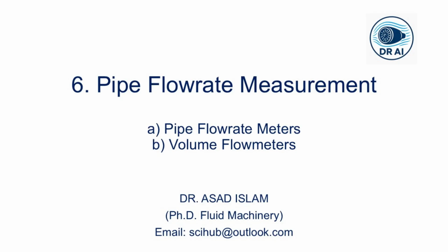We have come a long way together through this particular topic of viscous flow in pipes. We started with the fundamental characteristics of pipe flow: laminar versus turbulent, entrance regions, the fully developed flow. We derived exact solutions for the laminar flow. We explored the chaotic world of turbulence with its Reynolds stresses and viscous sublayer. We used dimensional analysis to create practical tools: the friction factor, the Moody chart, and minor loss coefficients.